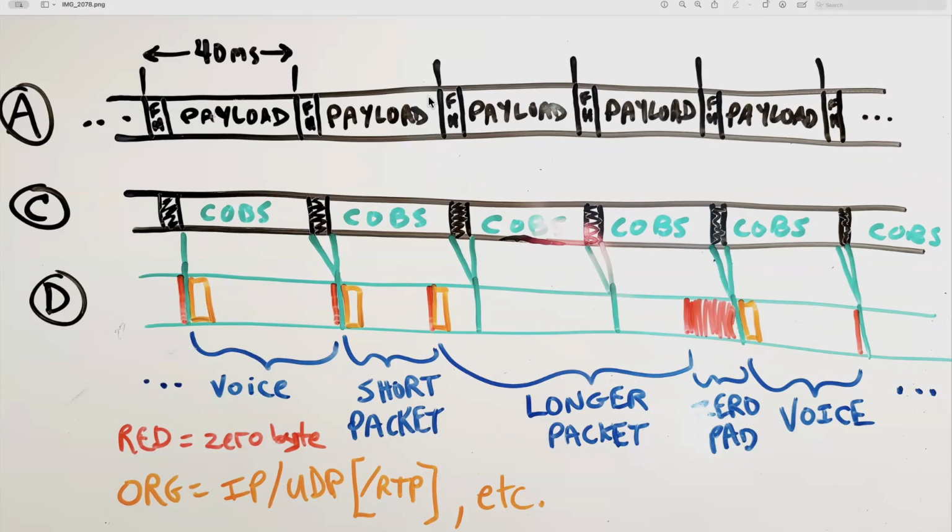We have 3 bytes available in the Opulent Voice header as reserved. It could conceivably go in there, and we could have our Opulent Voice header simply handle COBS fragmentation today. It would use up kind of a lot of that, but not too much. But you could compress it and make it sort of targeted. So there is a way to handle COBS fragmentation, which is not in the COBS protocol, but since we're fragmenting COBS packets here, we could go ahead and do it.